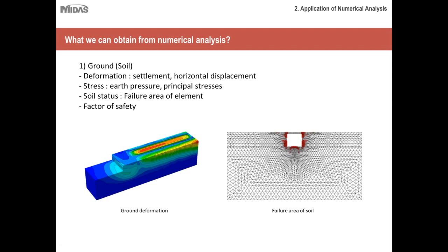as your soil is given more pressure or given more loading. The numerical modeling program can calculate to what extent the deformation will be. And then the stresses, earth pressure, principal stresses. So you can analyze the soil itself to see how the shear and axial strain increases over loading, over different weather conditions, such as changes in water levels, etc. And then failure of the element and factor of safety. These are two things that can be analyzed directly from the numerical modeling program itself.